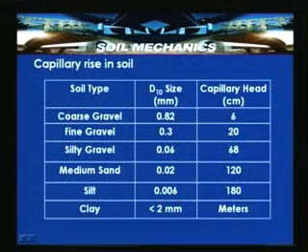So, when you consider different soils, let us look at how, with different effective particle sizes, they can rise above the groundwater table and remain saturated. A typical coarse gravel, which has a D10 of say 0.82 mm, can have a capillary head, that is HC, of about 6 centimeter only. Fine gravel, 0.3 mm, can have a 20 centimeter capillary head.